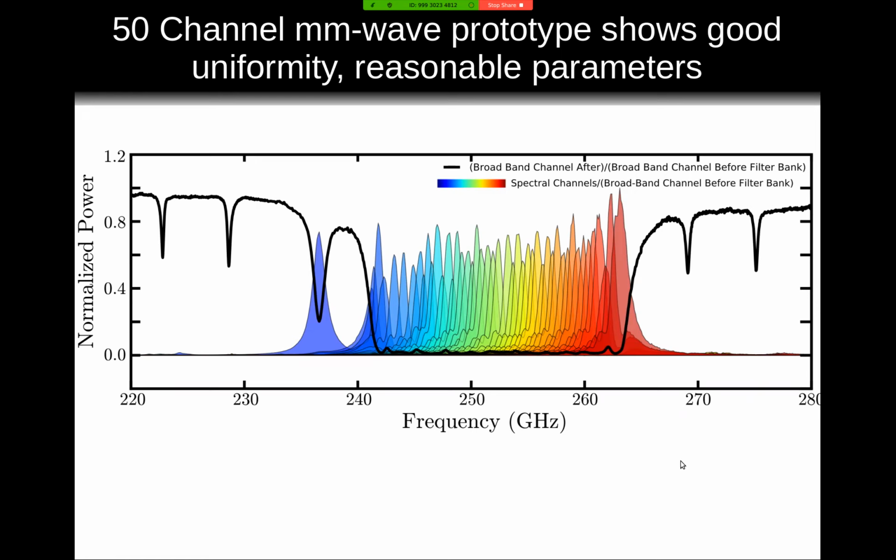To be honest, we've not tested that, but I'd be very surprised if it changes by more than we can measure. If you're at 1/10 of the superconductor temperature, the kinetic inductance is not going to change, and the dimensions aren't going to change. So it should be within the bandwidth that we measure.